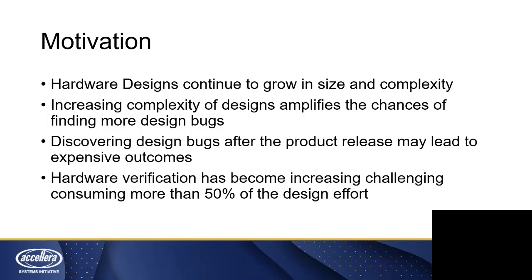For example, finding a design bug at the IP verification stage is way more costly than finding it at the coding stage. Current studies suggest that this is due to the increase in resources required to identify and bucketize bugs after coding.